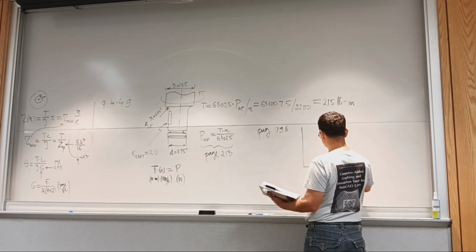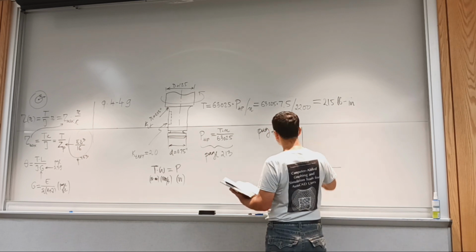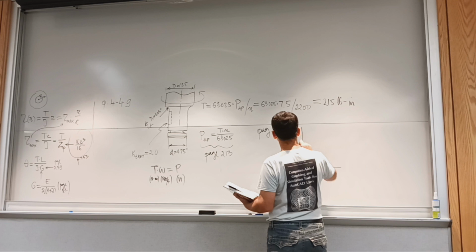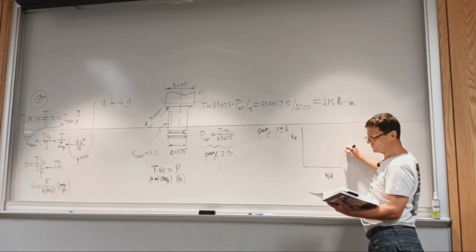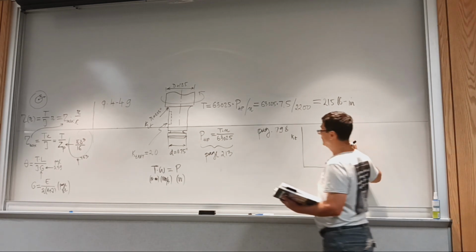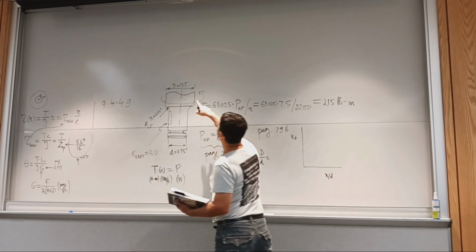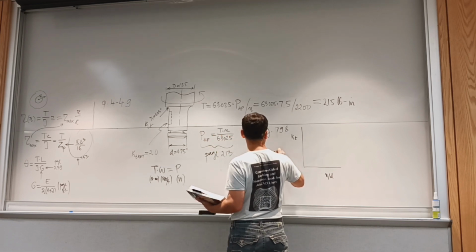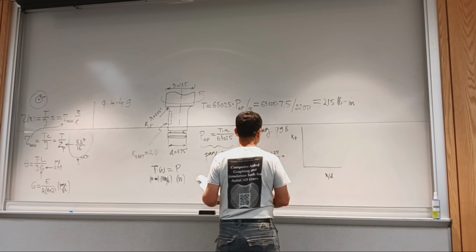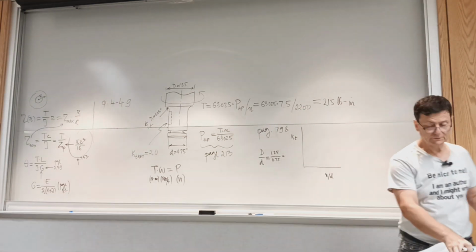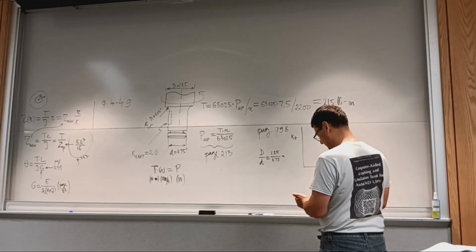So we have to calculate R over D, fillet radius over minor diameter, and then we read coefficient of stress concentrator on the vertical axis, and we need to choose the closest, or maybe it's readily available curve, D over d. So we have 1.25 over 0.75 for the curve.